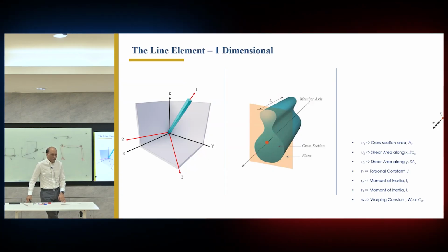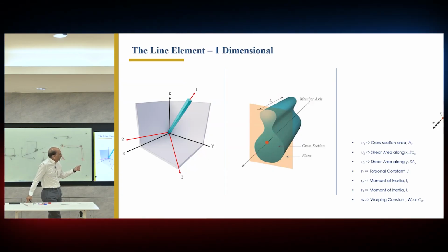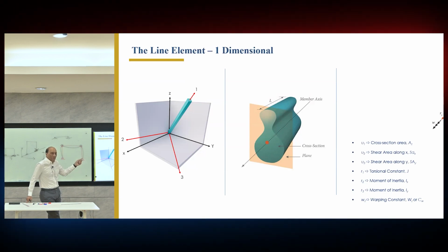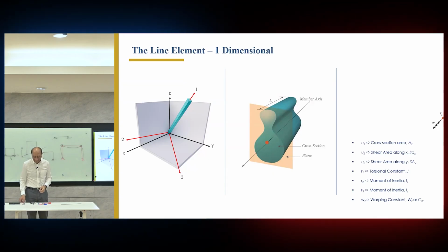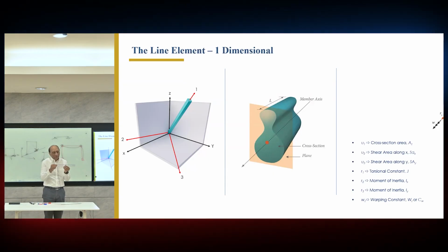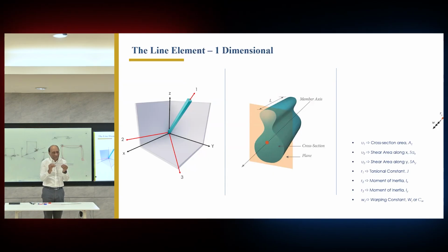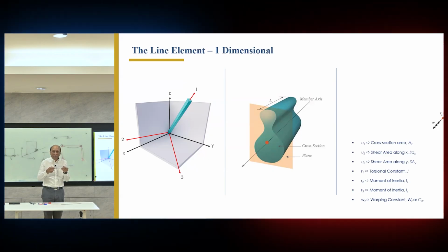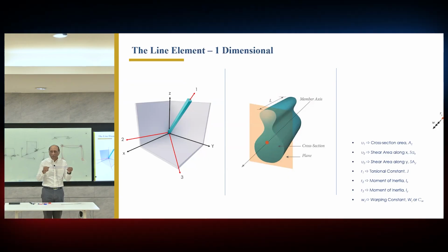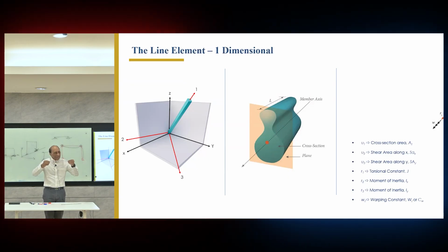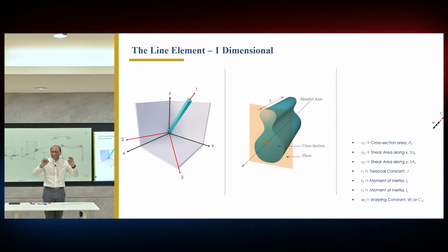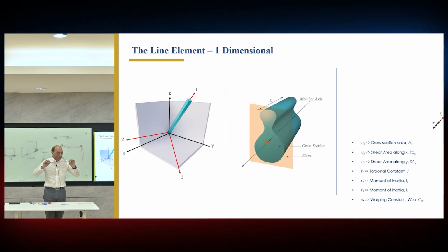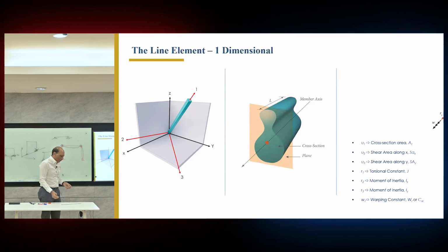And today we come back to this because now we need to deal with local axis, very important in the analysis, because the sense of bending moment will change. So for example, this way, moment of inertia is very different from this direction. So if you do not orient it properly, you will be designing in the wrong direction. You think you have put the ruler like this, but it could actually be like this if you do not fix the local axis properly. So everything will be wrong. So fixing the local axis is very important.